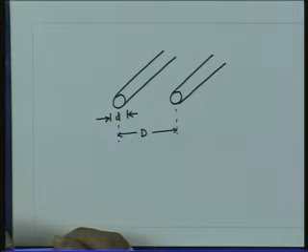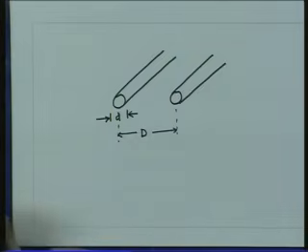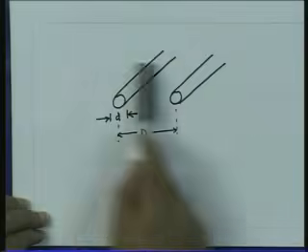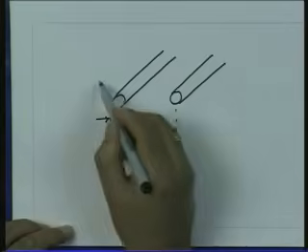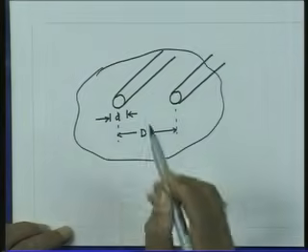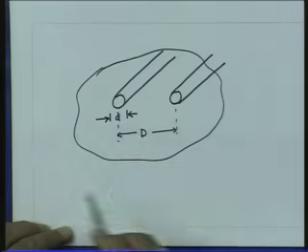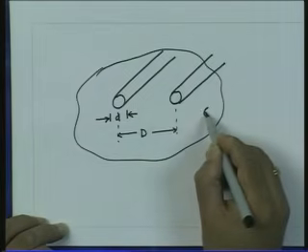You may see this structure whenever we have an open wire like a power line. You can also see this structure whenever you use the flat ribbon cable for connecting a Yagi antenna to a TV. The flat ribbon cable which runs from the Yagi antenna to the TV is essentially a parallel wire structure, and in that case there is no air medium, you have a plastic encapsulation on that. So, there may be some kind of encapsulation, and then this will be filled with a dielectric material with some dielectric constant epsilon r.